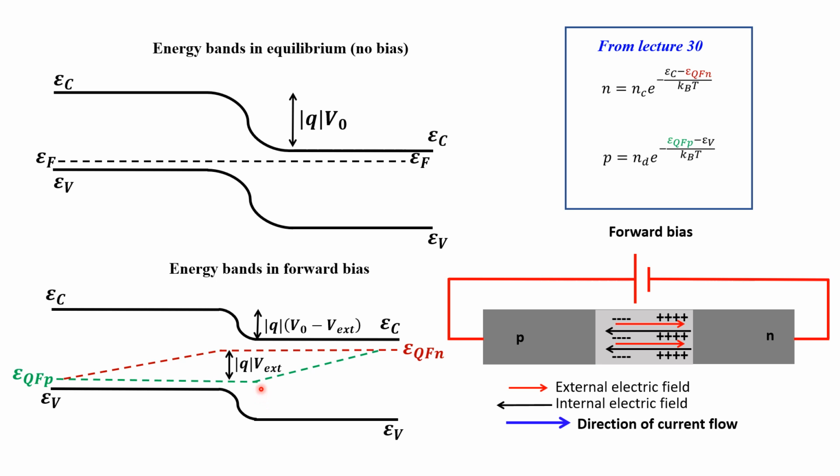But then, due to recombination, the concentration of holes decreases, so this distance starts increasing until it reaches the condition of equilibrium, until no new hole reaches a certain distance, all holes recombine. So this is what is represented in this point here.